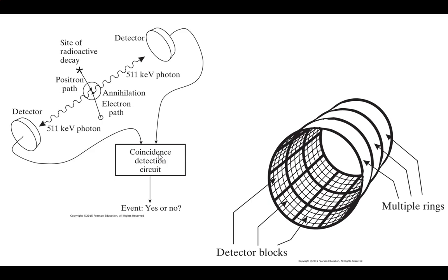I don't need it to completely have discharged, but if it's not going to discharge for a good 1,000 or more of my 10,000 time intervals, it's going to be really hard to accurately pick your peak with all the buildup that goes on. So I've got to get something in the small number of nanoseconds, then I'll still see another peak come off it and I can measure the peak. Does that make sense as an issue?